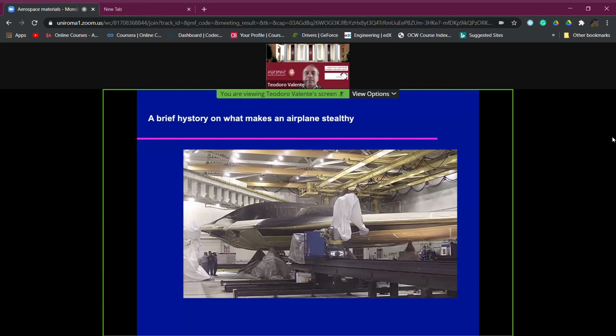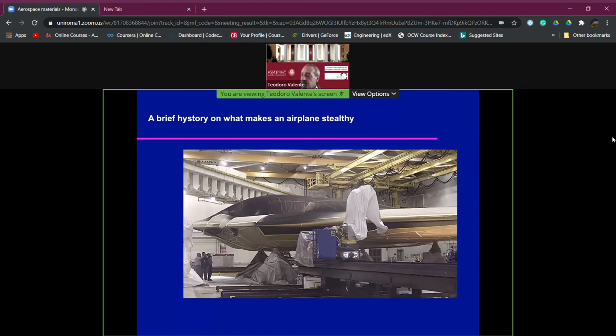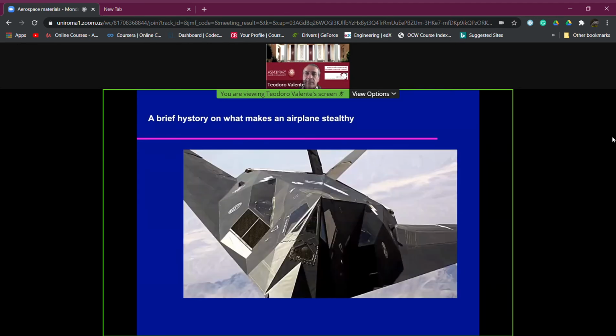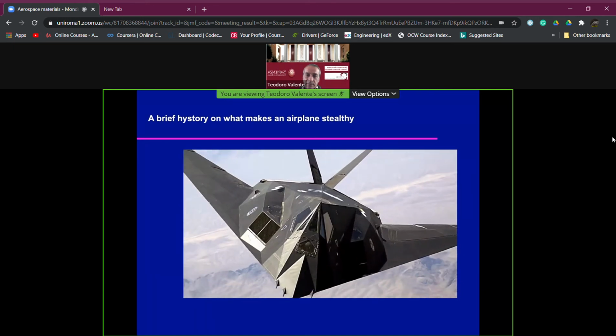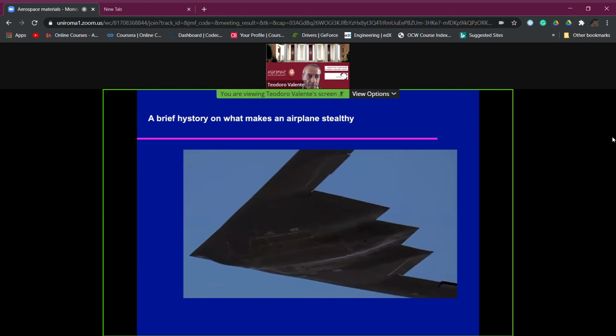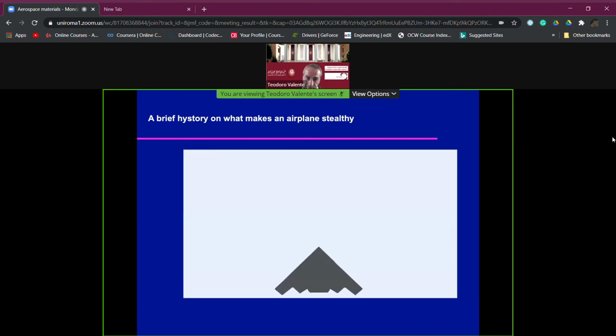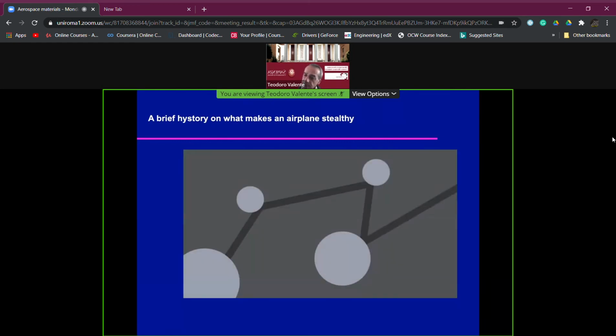Starting with the first item, the specific material used to coat the aircraft that is intended to be stealthy is extremely important. Radar absorbent material, or RAM, is material that is specifically designed to absorb the incident radar signals hitting the aircraft. On many stealth aircraft, a specific type of RAM is used called iron ball paint. As radar waves hit the exterior of the plane, oscillations are induced within the coating that alternate the magnetic field of the paint. This causes the radar signals to be converted into heat, which is transferred to the rest of the aircraft and dissipated instead of being reflected back to the source.